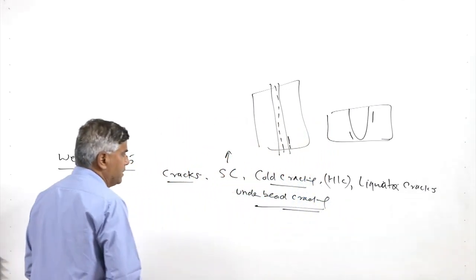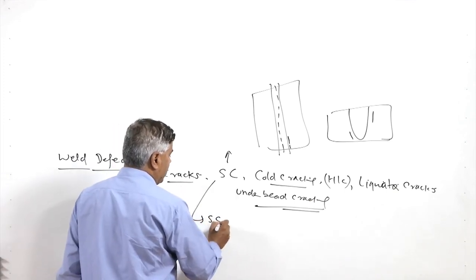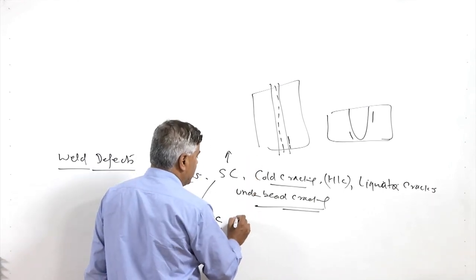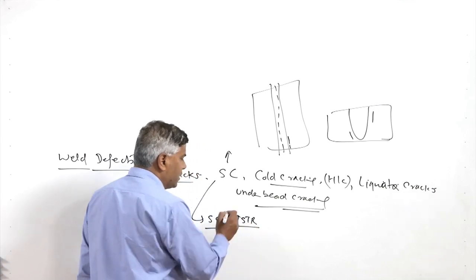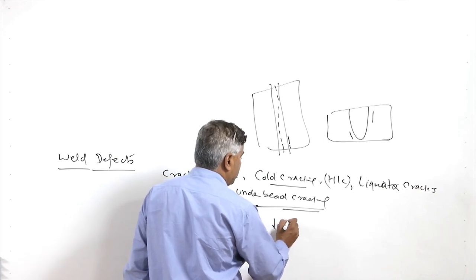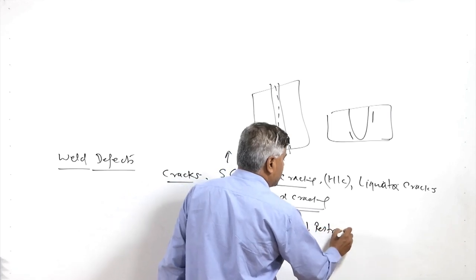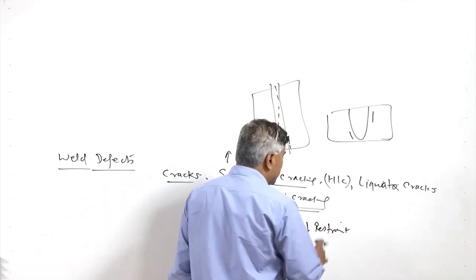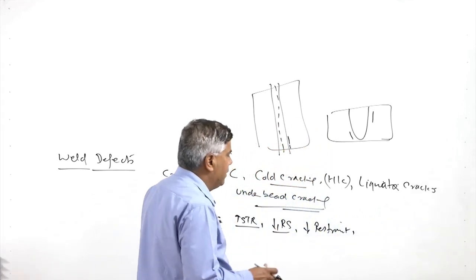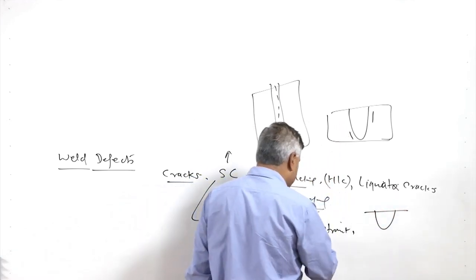with limited penetration. Now coming to the cracking related aspects, solidification cracking occurs mostly along the weld center line, especially in alloys with a high solidification temperature range. To overcome this, efforts are made to reduce the residual stress magnitude and the restraint conditions under which welding is carried out, and also to modify the grain structure, the impurities and the weld metal composition so that the solidification temperature range can be reduced.